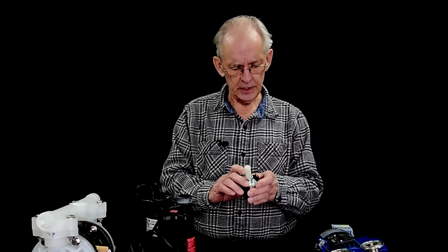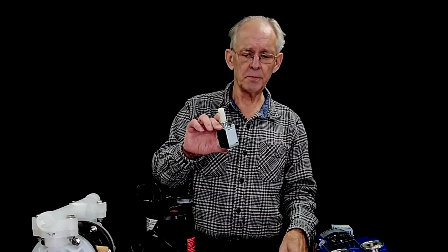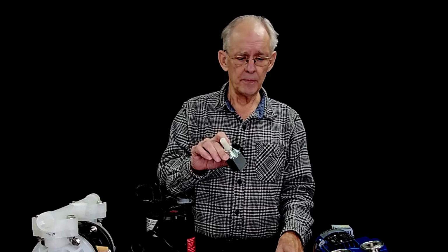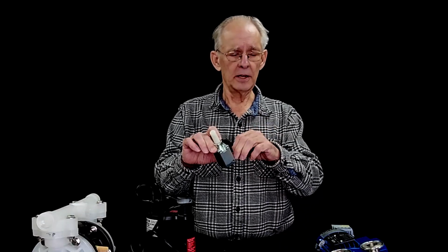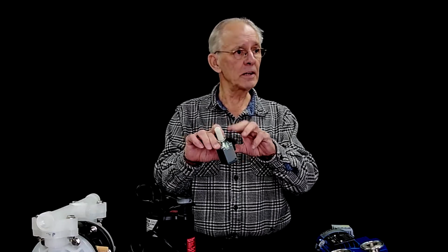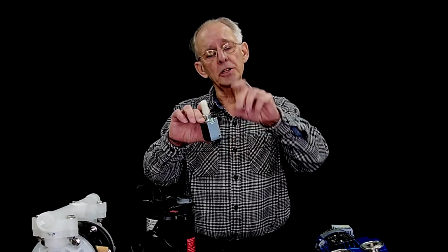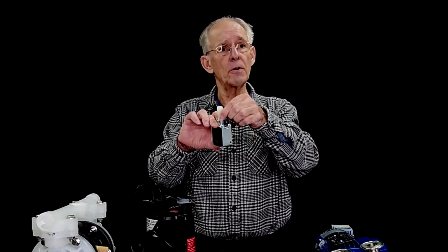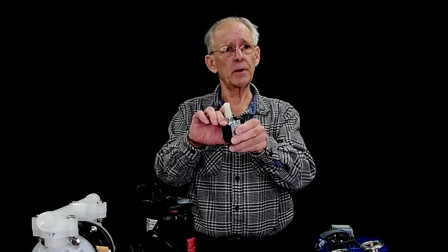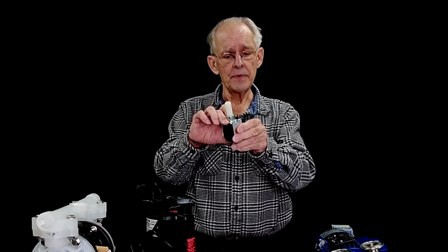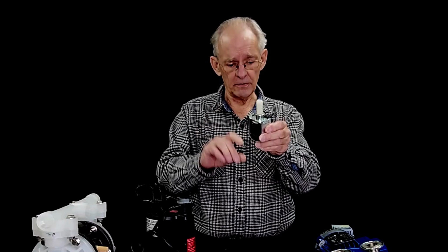Okay. Then we have this guy, and this is a positive displacement pump, but this is a solenoid pump. There's a piston inside that vibrates back and forth in time with the AC frequency of the line. So 60 times a second, the piston goes back and forth, and there's a check valve on one end and a check valve on the other end, and it is a positive displacement pump as well. However, again, it is not reversible because it depends on check valves.